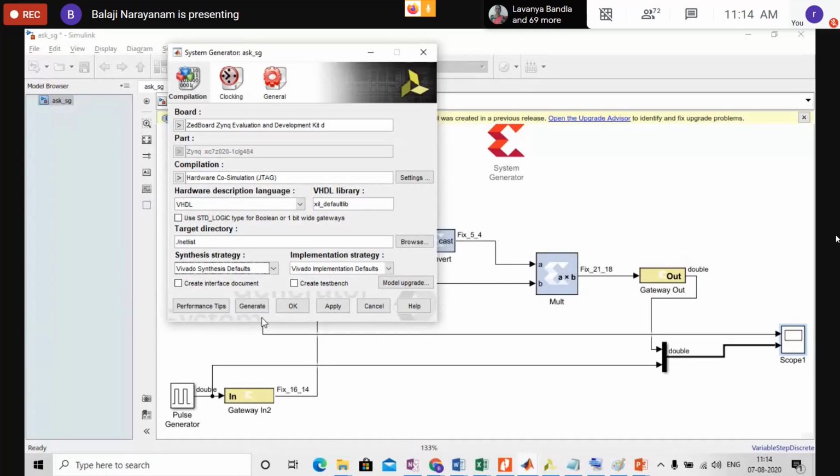See, why do we go for VLSI implementation? Three major advantages: delay gets optimized, area gets optimized, and power gets optimized. I may target all three parameters, but achieving all three simultaneously is difficult because power P equals C V squared F. Power is directly proportional to the frequency of operation.